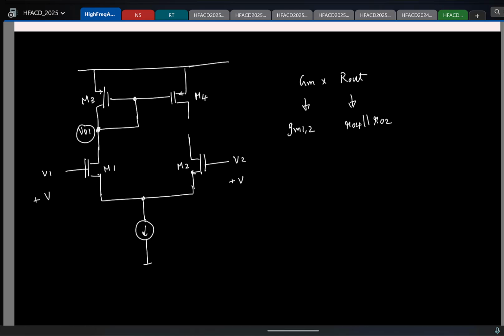And to again explain it, if you want to find the up and down resistance, the brute force way is you break this node, right? Apply 2 test voltages, the same test voltage actually. You find the current that flows up this way, and this ideally will have contribution from both the voltage sources.